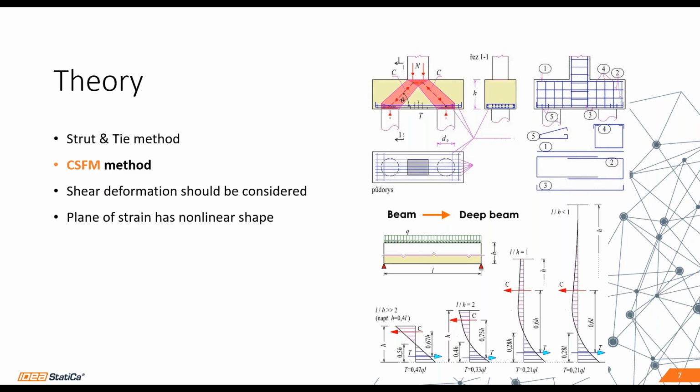Some brief theory behind pile caps, how they work, what you should consider. As I mentioned, you should use a different approach than the standard beam theory. Maybe you are very familiar with the Strut and Tie method, which can be used for design and code check of pile caps.